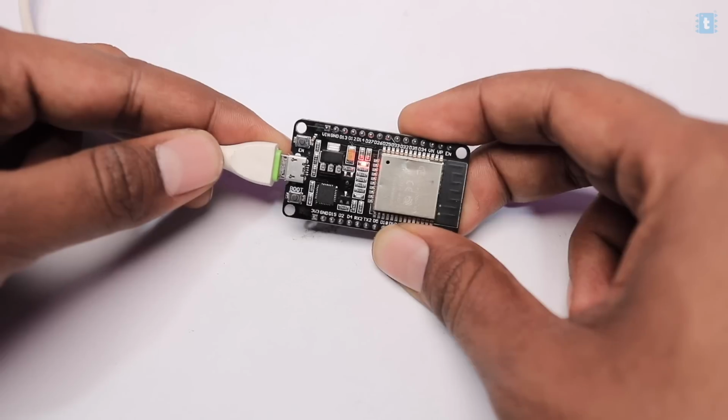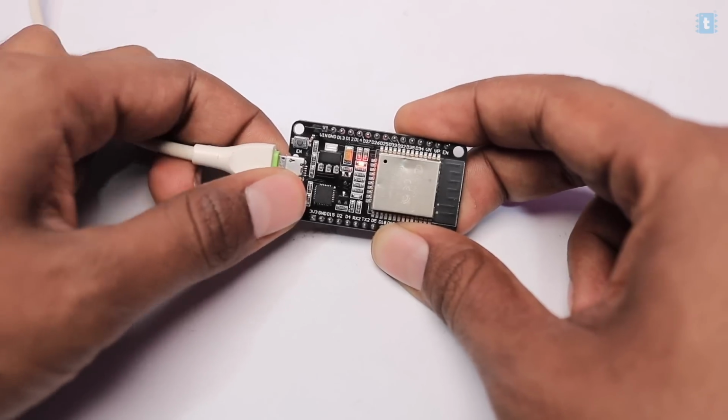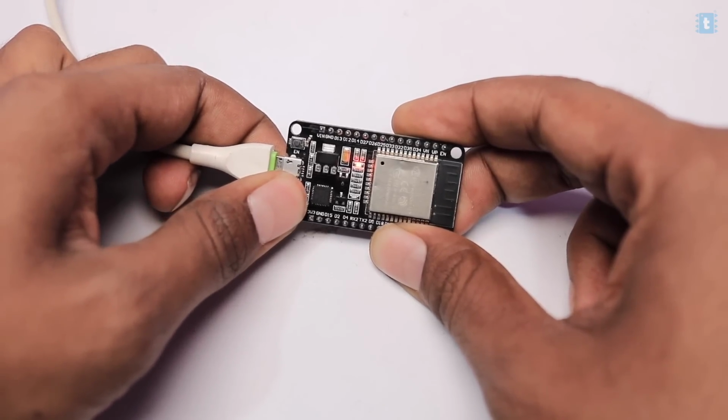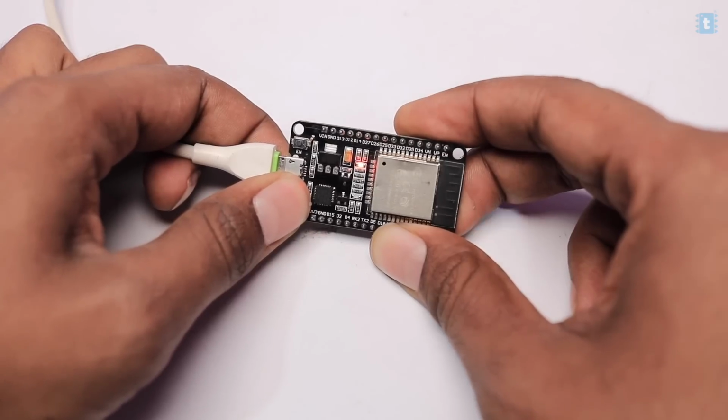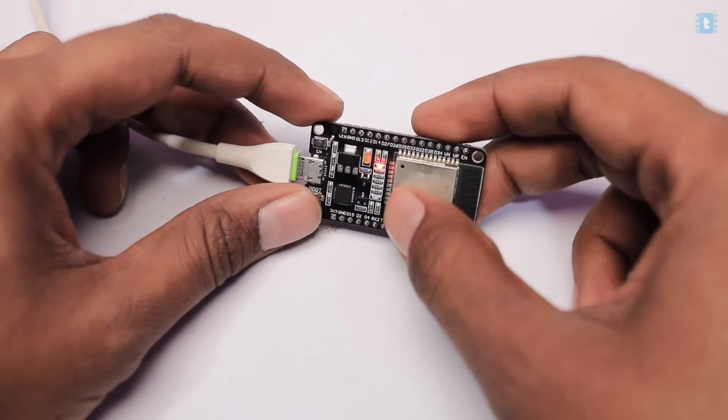Now here one question arises, how to change the Wi-Fi credentials in case we want to switch to a different router? Well, that is a very simple and straightforward process. Let me show you. So on the ESP32 board, you need to press the config button, which by default is the boot button, for 3 to 5 seconds and then release it. You'll observe that the onboard LED will start blinking. Now this indicates that our ESP32 board is ready to accept the new Wi-Fi credentials.